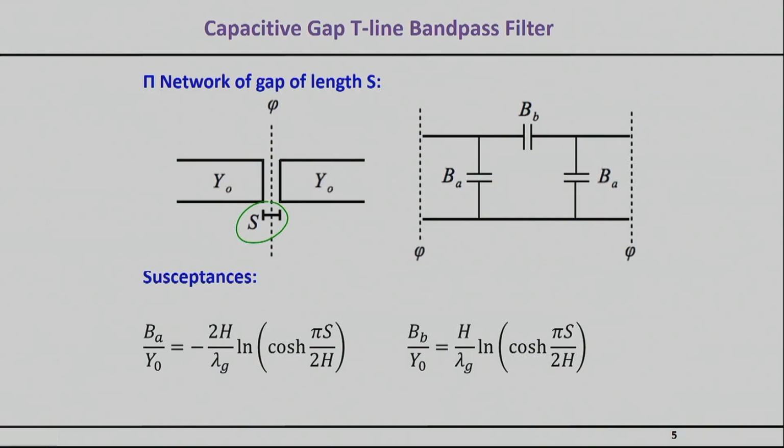As you can imagine, this gap is nothing else but a capacitor. That's the most physically intuitive feeling that comes. But in addition to this intuitive understood capacitance, because you're having fringing fields coupled from one to the next, you also have these two shunt capacitances, which are reasonable again because you have some substrate and some ground plane. And so this equivalent circuit that you see right there is actually pretty simple, and it would apply, I would say, to any type of a gap-based coupling.